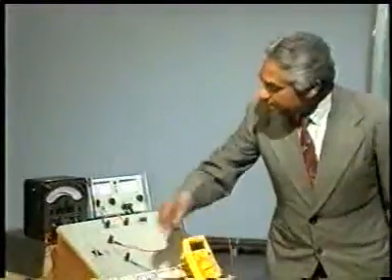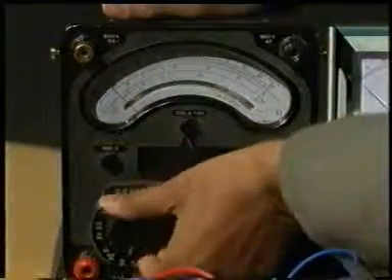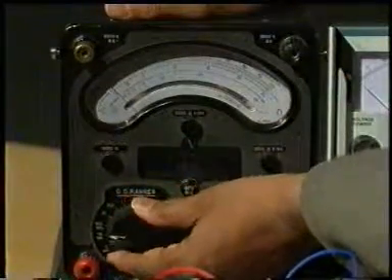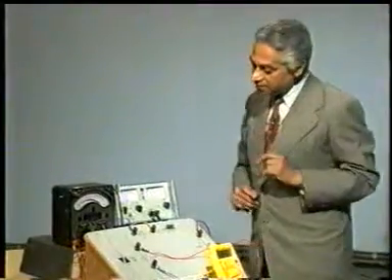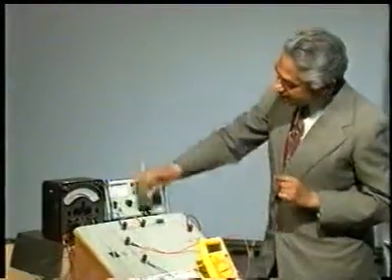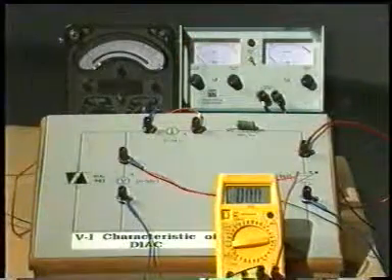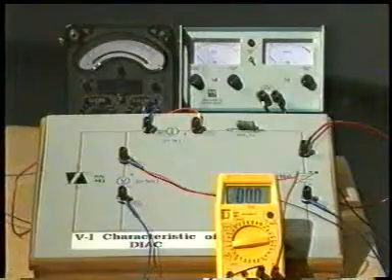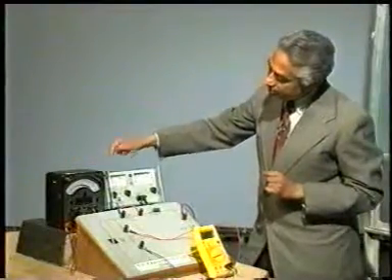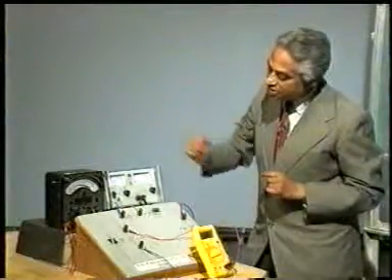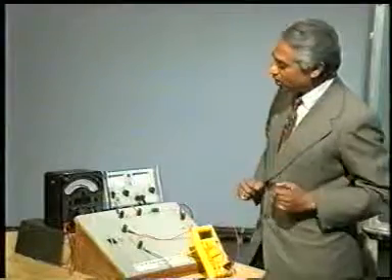For that, I will change this multimeter into microampere range, because the current there is very, very small. So I put it in microampere range, and I will put the voltage in steps. I will increase the voltage in steps, and I will take down the readings correspondingly to this current, the voltage here, voltage and current. These two readings I am going to take. I will get about 2, 3 or 4 readings, and then I will plot the characteristic.